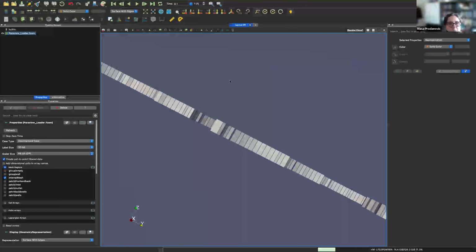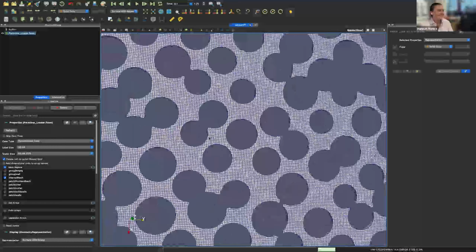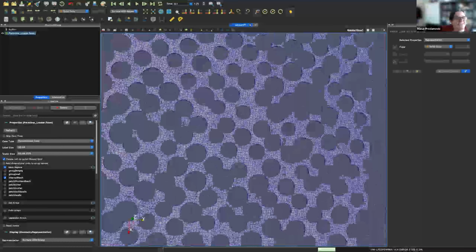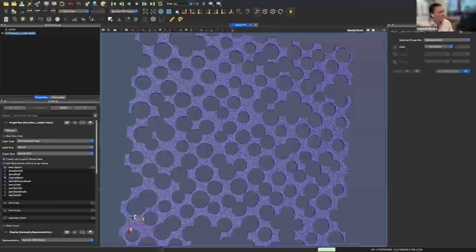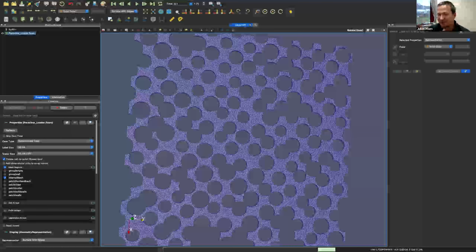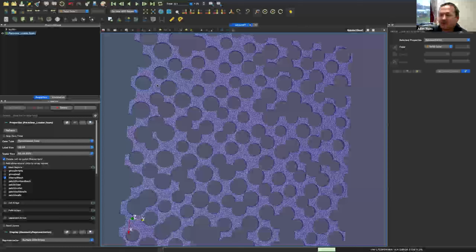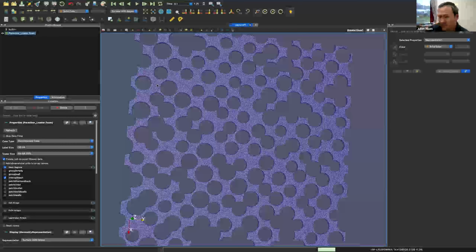So it's become a sort of quasi 2D or quasi 3D. I don't know how you want to look at that. No, it's a 2D finite volume system, where the boundary at the top and the bottom don't exist here. But when you calculate, there is a volume of the cell. But the boundary on the front and back don't exist.